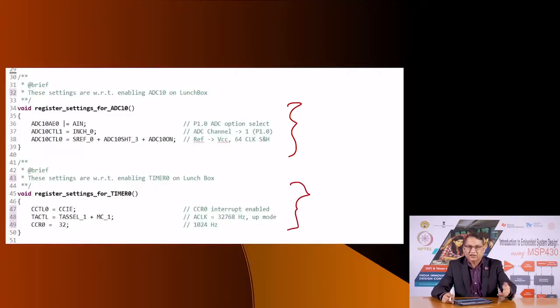Now, this is an additional subroutine in this program, because we are using the timer to generate an interrupt at roughly 1 kilohertz using the internal 32 kilohertz clock. By dividing it appropriately, we are generating a timer interrupt 1000 times a second, that is, at a rate of 1 millisecond. So, the Charlieplex LEDs will be refreshed 1000 times a second.